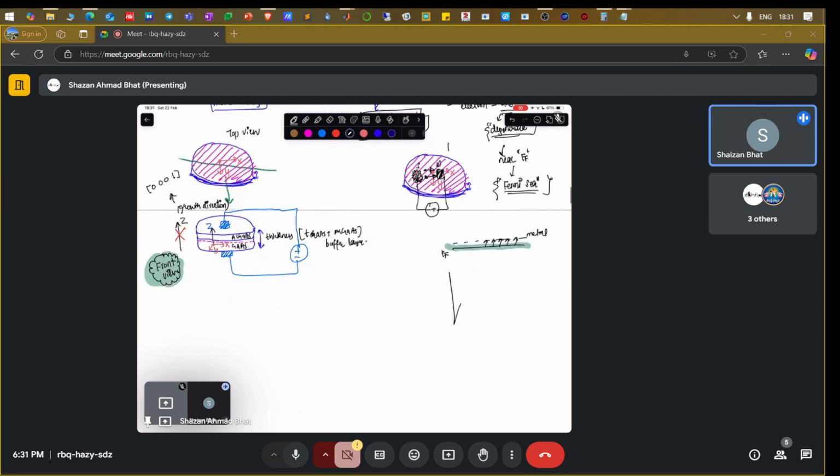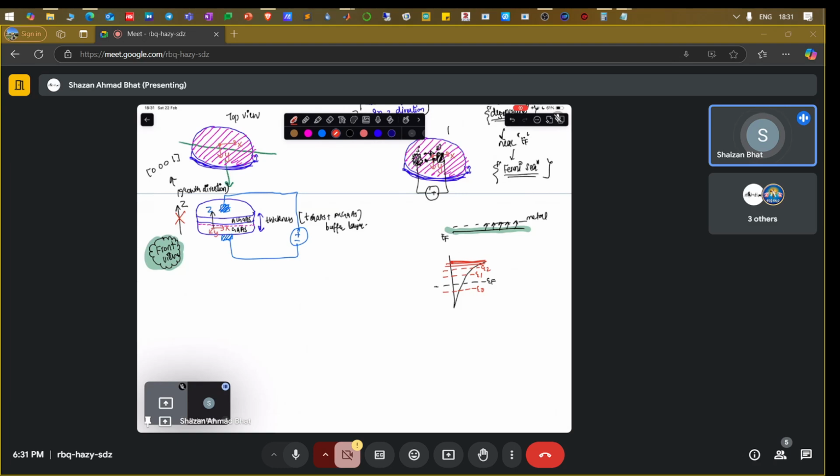You have the confinement, you have the triangular potential well, you have the Fermi level, you have the first energy state, the eigenenergy, you have the second eigenenergy state. As you go on, you have the third, and it becomes continuous as you go up above the conduction band, as you go to higher and higher energy states.